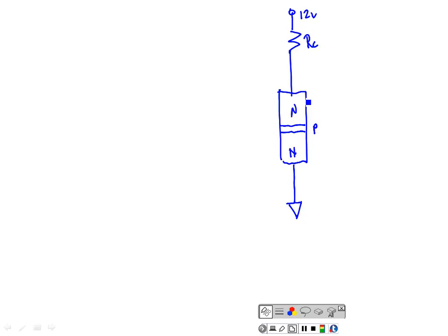So we're talking about current flows down in the microamps or the nanoamps, because there is a path current can get through there. Y'all know there's current flow through insulators, right? Because there's no such thing as a perfect insulator. It's just that the number of electrons in there to be able to push are so small, they're bonded so strongly together that almost no current moves.